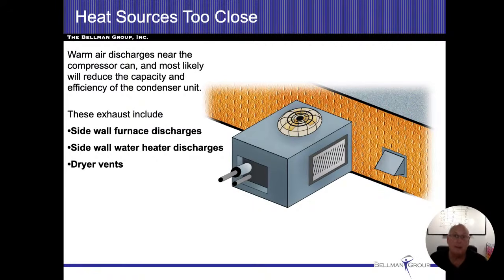However, the condensation that comes off of a sidewall vented furnace, because it is a condensing furnace, is very caustic. And if that gets blown onto the fins on a regular basis in the winter, we're going to start rotting and deteriorating those fins like there's no tomorrow. So that in itself, I think, is a big deal. And yeah, the air shouldn't be blowing on the fins.